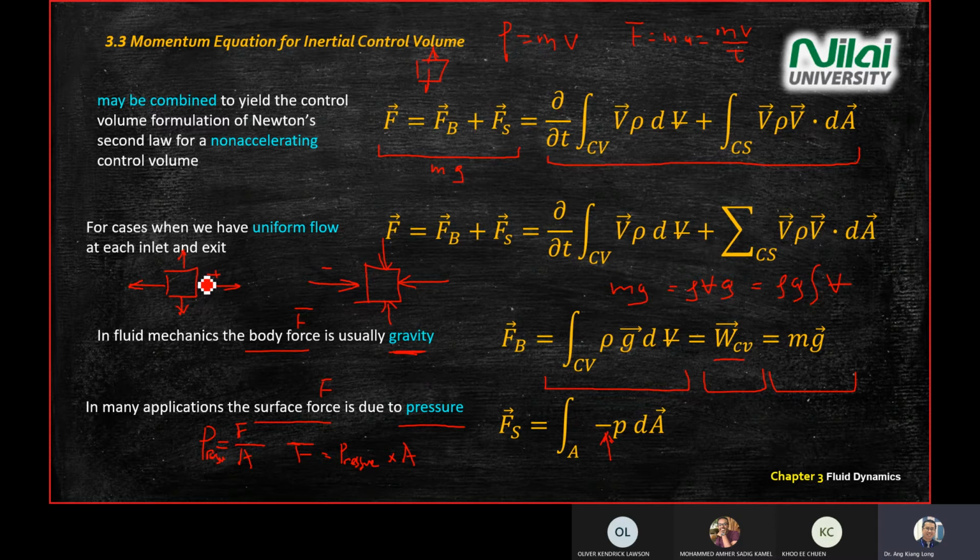So this is a universal notation to explain your answer after you calculate. Let's say you calculate the surface force and you get a negative. It means that the pressure or the force is compressing the surface. So remember to carry a negative sign when you build your equation.